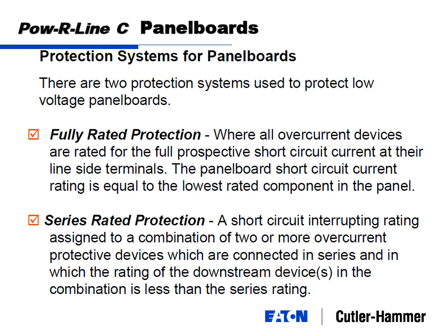feeder breakers. So my feeder breakers might only be rated to handle 10,000 amps, and therefore they've got 10,000 amps worth of insulation and cost associated with it, and obviously they're going to be cheaper to make, cheaper to sell, cheaper to install. But by series rating this, we've put these two breakers on a bench at UL and guaranteed that one of those two breakers will trip and take the circuit offline and protect the panel board.